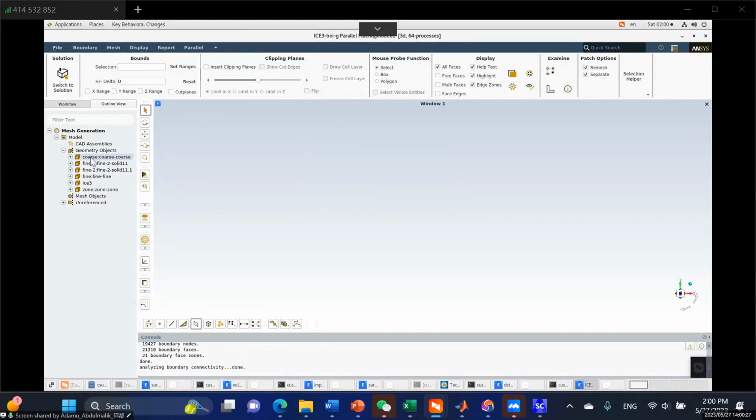Okay, so I want this mesh size to be equal to 1 millimeter. I want this mesh size to be equal to 0.5 millimeter. So faceting helps you to put these values first and then save it. Then you will need to import the surface mesh using these saved size fields that you have created from the faceting option. I don't know if you understand. So let's see it practically here.